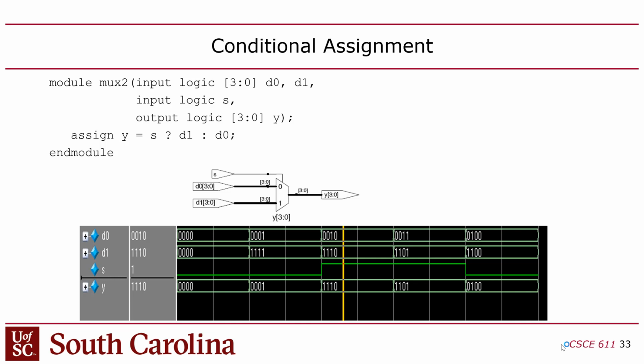Well, that's done essentially through multiplexers. So when you configure an FPGA, when you program an FPGA, one of the phases of that is setting up the LUTs, the logic tables. That's when you're selecting where you want to put each one of your gates on the FPGA. That's called placement. And then the routing part is where you select all the muxes that connect the gates together, right? So the mux is a way to programmably connect wires together. But you can also build muxes on top of an FPGA additionally, which is what we're going to do.